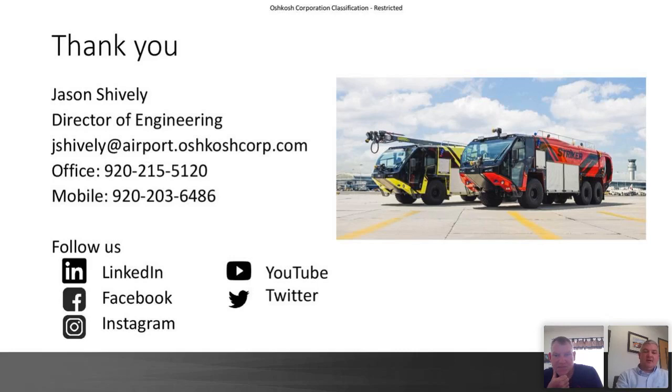We're adding the flow meters and the controller, and then we're using the foam flush circuit. The controller is tricking the truck into using the foam flush circuit instead of the actual foam system to pull the water out of the water tank and put that through the foam system. But I'd say probably 90% of the foam piping and foam proportioning components are the same as a standard foam system.